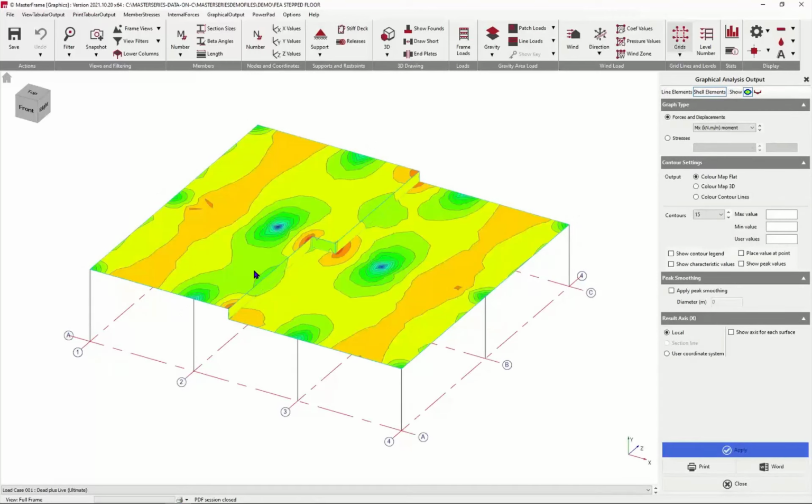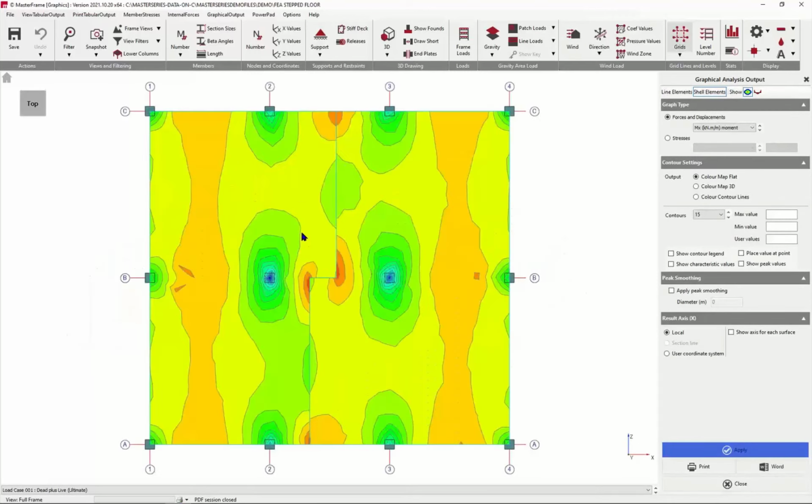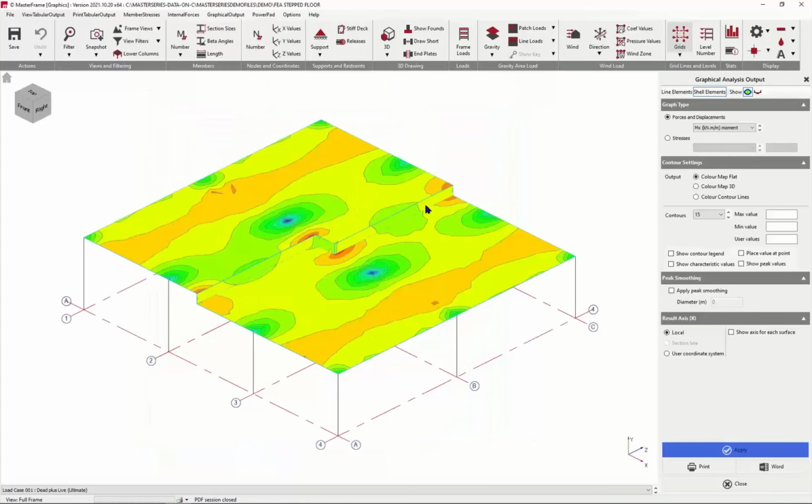And you'll see what's here carries forward and what was here carries forward. So although if you were using our slab design program, you wouldn't be able to design the wall, whatever the moment here is carries through the steel down and then across, unless you're in a very, very deep wall. So it's not that big of a problem.